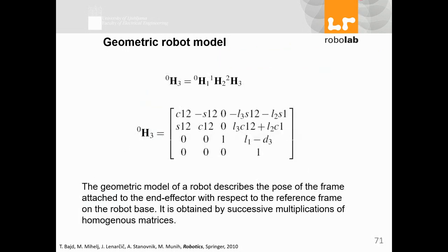When I combine the three together, from the origin, from the base to the end effector, what I have is matrix 1, matrix 2, matrix 3 multiplied together.